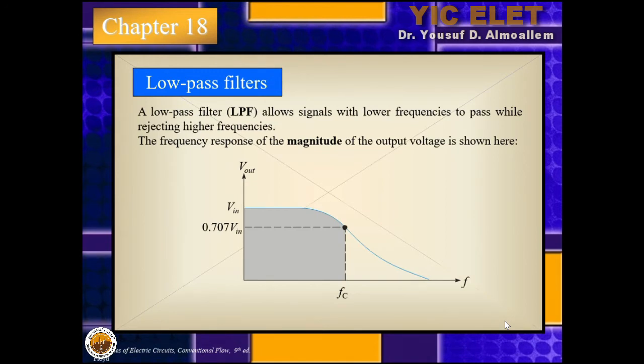Okay, this is how a low pass filter looks like. So this is a low pass filter where this is the voltage input and this is the voltage output plotted against the frequencies. Now this is a Bode plot, so this is a logarithmic scale of frequencies, and this is a decibel plot, or it is a linear scale, so semi-log plots.